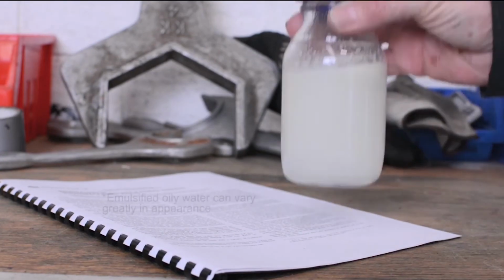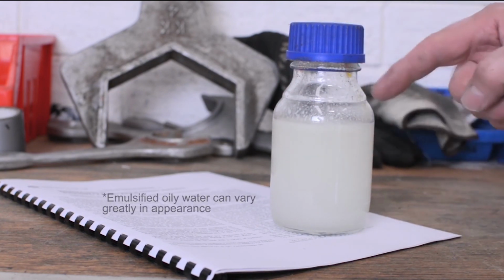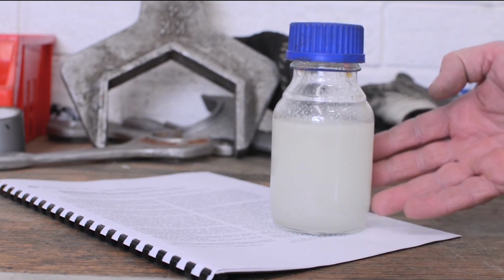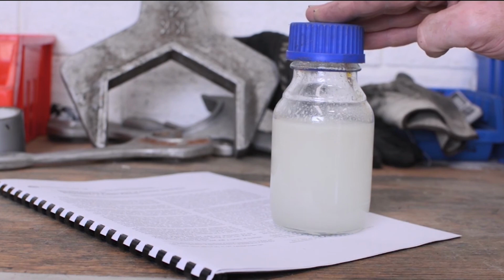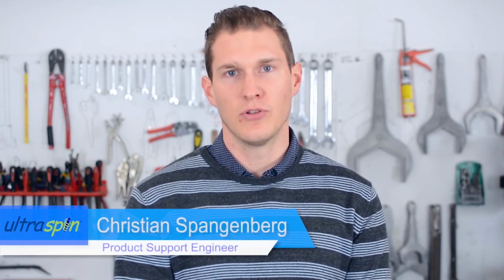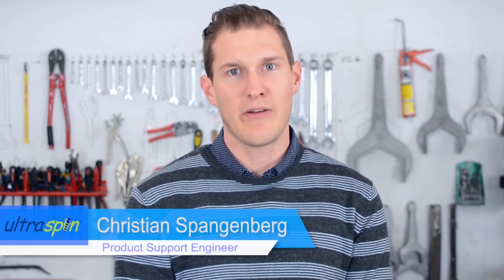The second sample is generated from our test rig using the ASTM testing method. And as you can see, there's a lot more emulsification, so this is a lot more representative of what you would find in most industrial oily water applications. As you can see, there is no one-size-fits-all oily water separator certification standard, and no separator can guarantee that it will achieve 5 milligrams per litre discharge concentration just because it has received a certification.